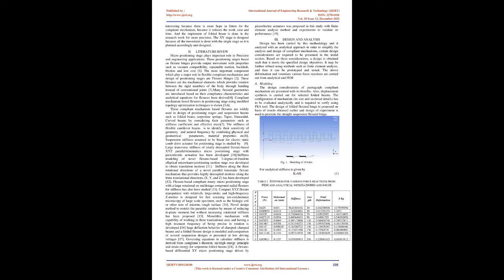2. Literature review. Micro-positioning stage plays an important role in precision and engineering applications. These positioning stages based on flexure hinges provide output movement with properties such as vacuum compatibility, repeatable motion, no backlash, no friction, and low cost. 1. The most important component which plays a major role in flexible compliant mechanisms and design of positioning stages are flexure hinges.